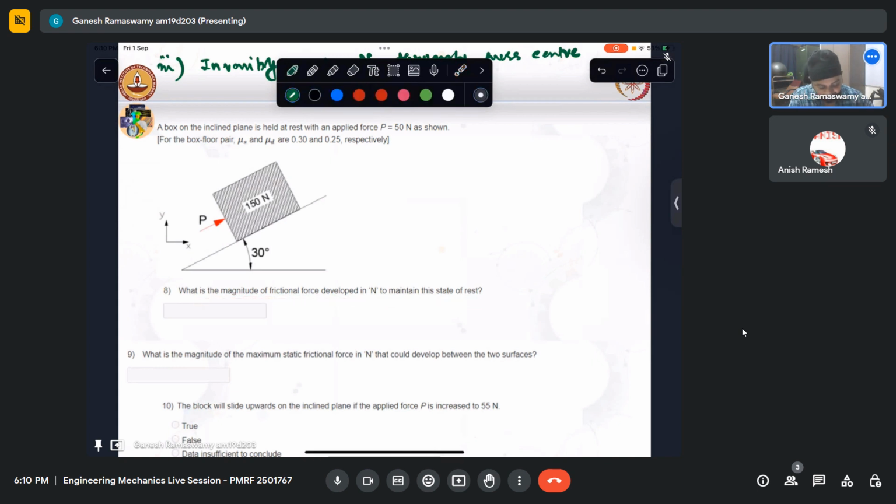So essentially whatever we have been doing in equilibrium is the same thing we'll be doing, except in friction one more force gets added up, whose magnitude could be known in a sense that when motion is impending, we know it is mu s. When the motion is not impending, we might have to find that.